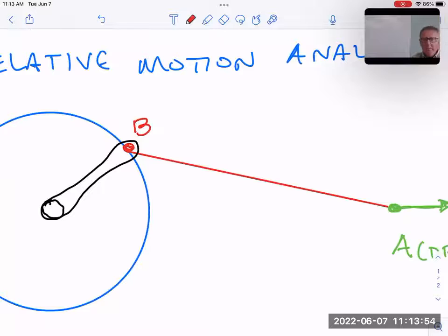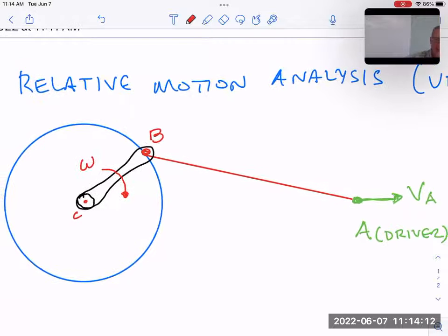Yeah, there's two ways of looking at it. There's this angular velocity right here, and I'm going to give this point a name too, C. We might call that omega, which is the angular velocity. And notice, based on where I have this drawn, do you agree that it's rotating that direction, which we'd call clockwise? So in the position I happen to have it drawn, that pole is going to rotate clockwise. So we can talk about the angular velocity of it. If we were to actually talk about just the straight velocity of it, does it make sense it was this? That's actually the velocity of B.